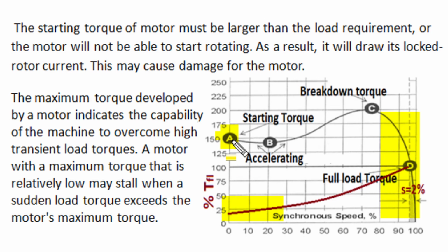And with double line current, when a motor is started, it won't create much trouble to other appliances connected to the same supply by voltage drop problem. Now the maximum torque capability or breakdown torque capability is also very significant, as in certain load conditions all of a sudden the mechanical load requirement on motor may get increased, and normal NEMA B design has breakdown torque 2 times of full load torque.